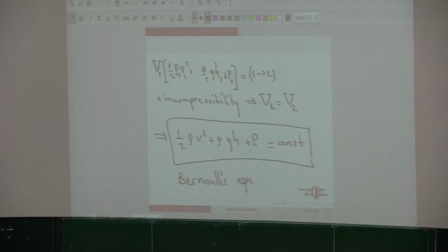Then he increases the velocity of the air at the top. But we know that this is constant. As he blows air, it leaves here, and eventually it will come here. When it comes here, it stops. Its speed is almost 0, because it's spread out. The pressure here is P0. So at this point, when V is almost 0, P is equal to P0.